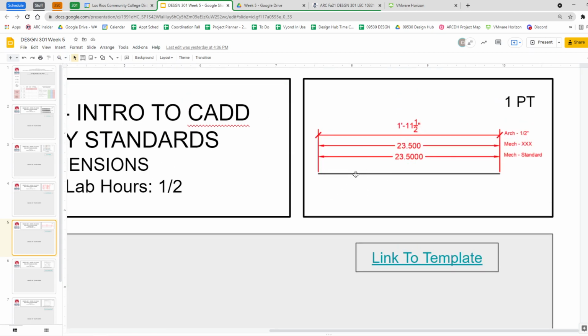This one, again, is a little bit different. In the other one, I was doing a distance measurement and AutoCAD was talking to me. Now, your units can be set however you want, and you can make your dimensions look however you want. So you're going to use a set of dimensions and then a units, say decimal inches, and then you're going to be able to go and figure out how to make these look like this.